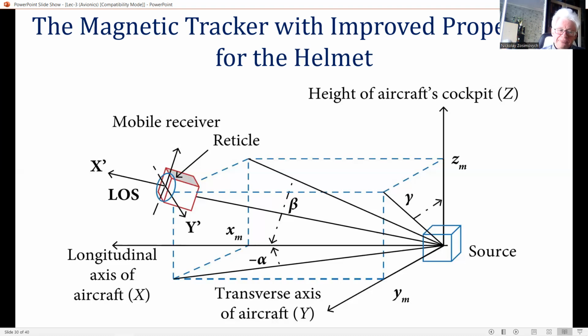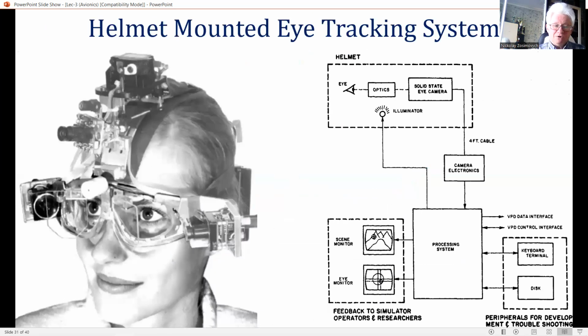It has been shown, however, that the pilot's gaze can still be maintained on the target while the pilot is experiencing low-frequency buffeting type vibration. This is because the control of the eyeball, and hence the direction of gaze, by the eye muscle has a much faster response than the control of the head position by the neck muscle. The eyeball servo has, in fact, a bandwidth of several hertz in control engineering terms.